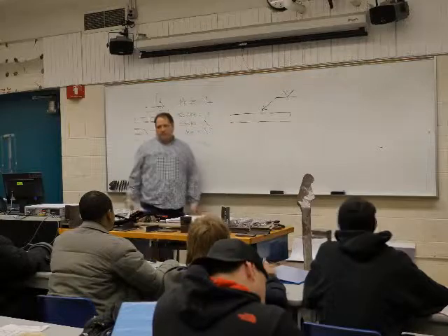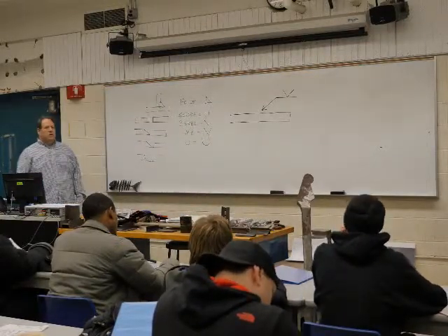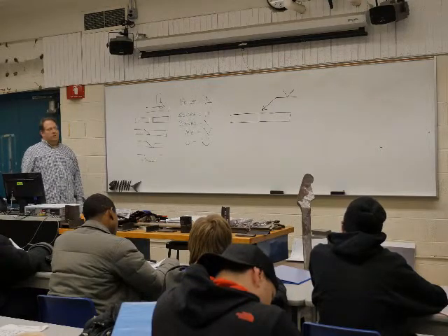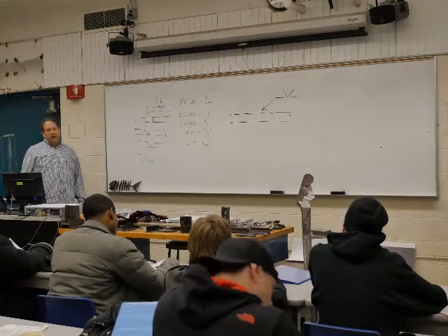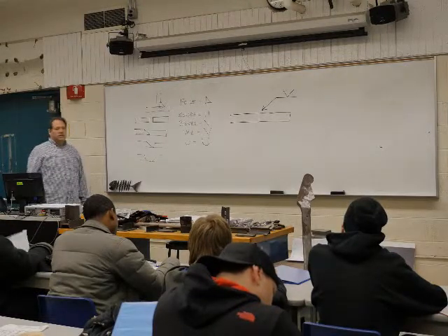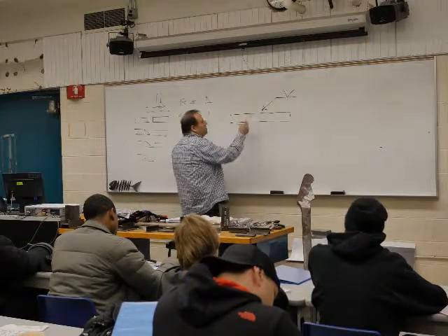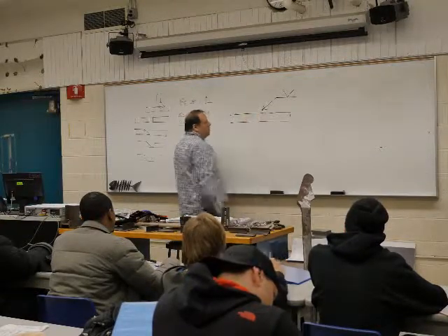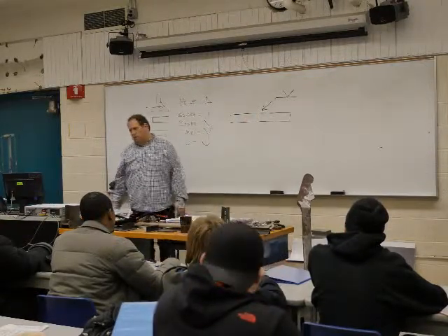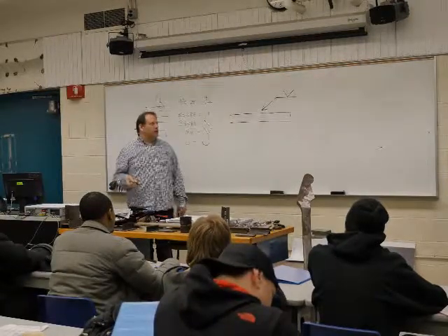So we have what? We have a V groove on what side? On the other side, so that's the bottom. So we have to prep this in a V. Well, we don't have that dimension yet. This is where we start stacking information on these ones.